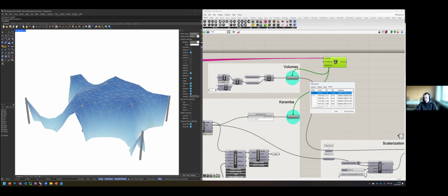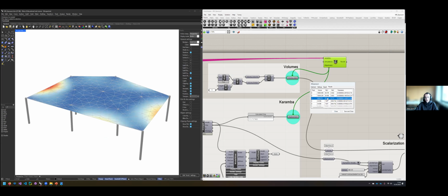And on this Pareto front now, you will find points that have very low volume but a high displacement, but also points that have larger volumes, but little displacement, right? So this is now exactly the trade-off that I was talking about. So this particular instance has a volume of 40 and a displacement of 0.7. And this first instance had a volume of 7 and a displacement of 147.